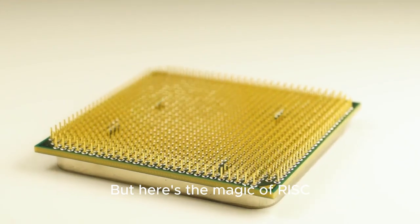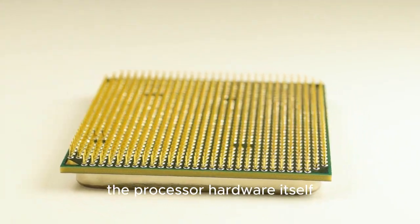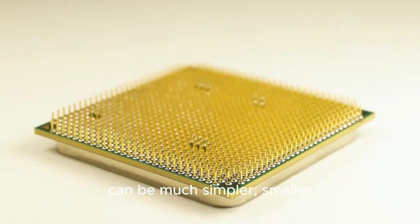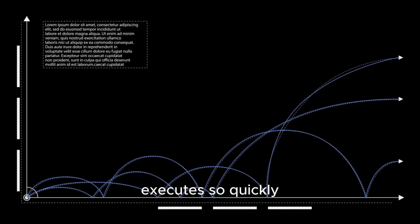But here's the magic of RISC. Because each instruction is so simple, the processor hardware itself can be much simpler, smaller, and more power efficient. And since each instruction executes so quickly, you can often complete the entire sequence of simple instructions faster than the single complex instruction on a CISC processor.